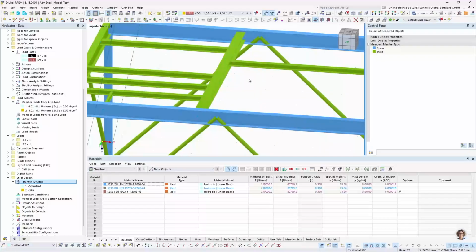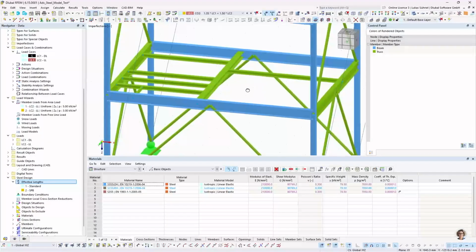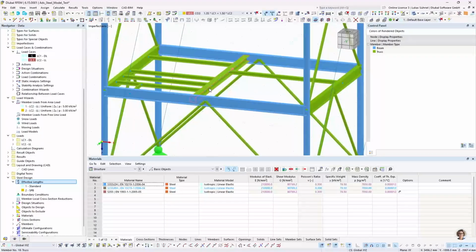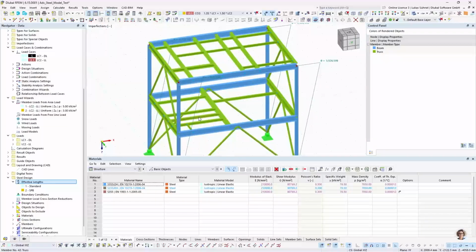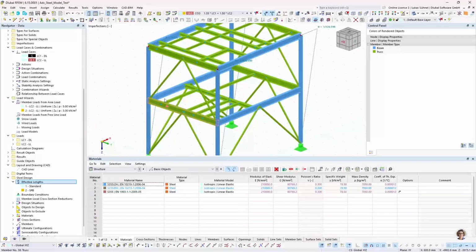And my idea is, let me first check it as single span beam. If the design ratio for my stability check is not okay here, if it's above 1, then I can still think about assigning additional horizontal supports. If it is okay, then maybe I can live with that. Yeah, maybe it's conservative. I'm on the safe side. Maybe not that economical. Well, it depends if that's necessary or not. All right, and then I have a couple more beams that I have no settings for so far.